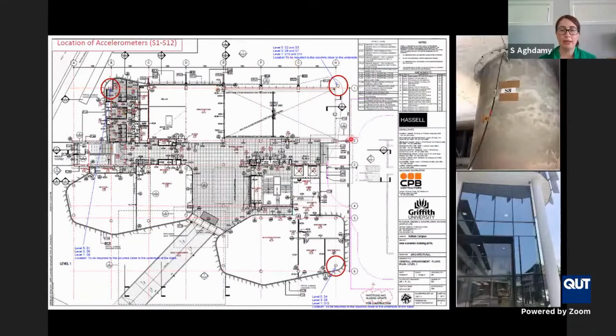It's not a rectangular plan. It's not a rectangular building. It's semi-rectangular, and that's why we've got the sensors installed on 3 main corners. These are single-axis accelerometers. On this particular corner of the building we've got 2 accelerometers, one measuring in X direction, and the other in Y direction. And then we've got single-axis accelerometers installed at this corner and this corner of the building. One of them is measuring in Y direction, and the other one is measuring in X direction.